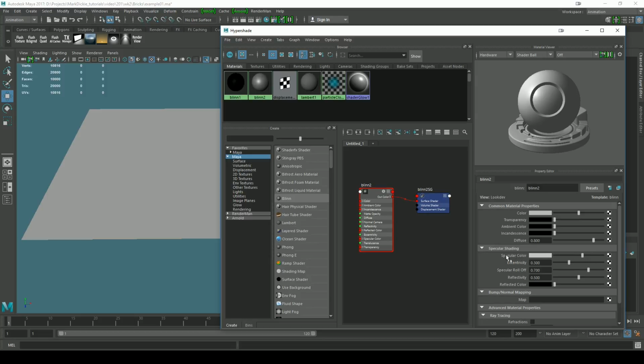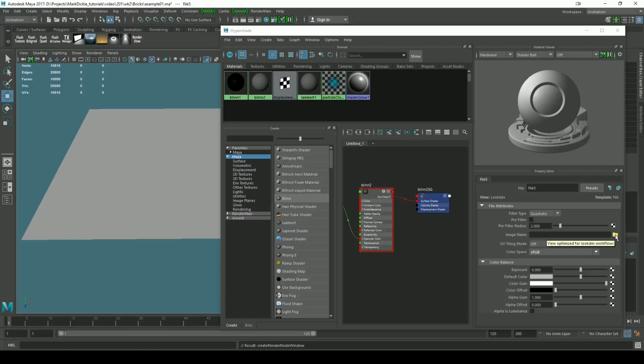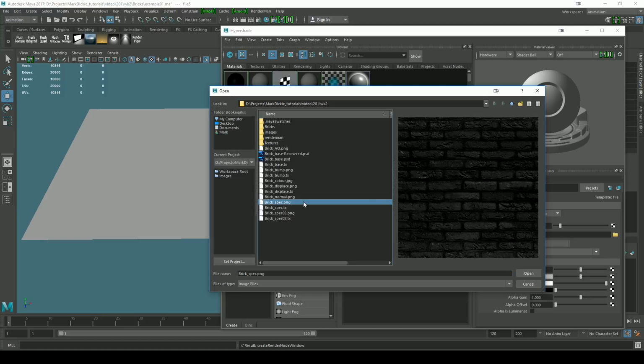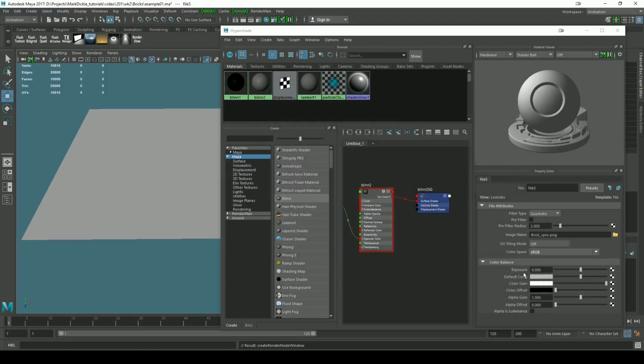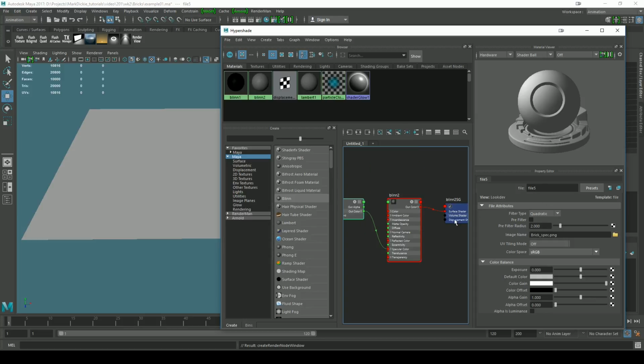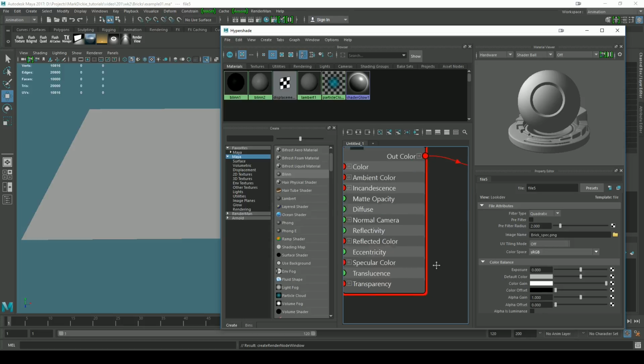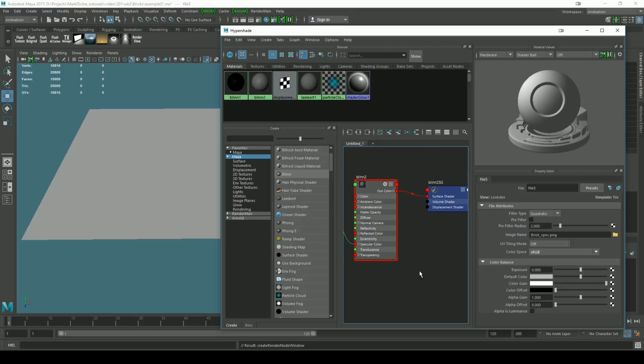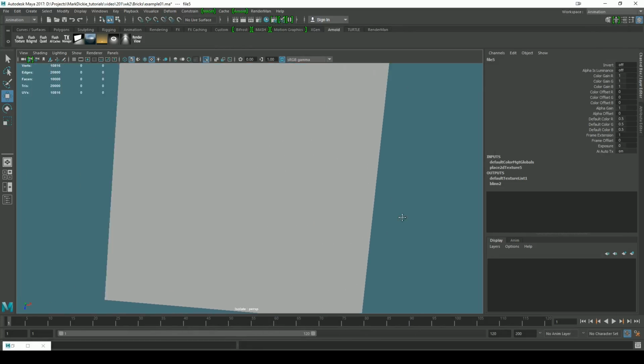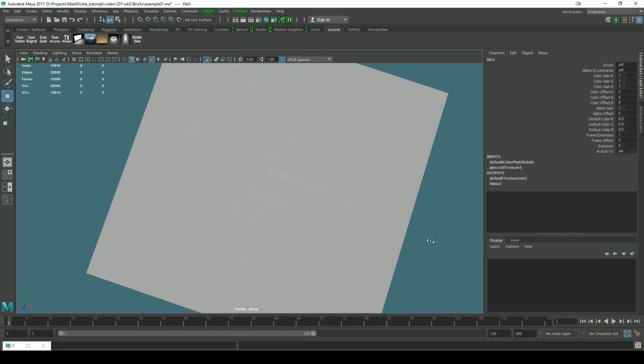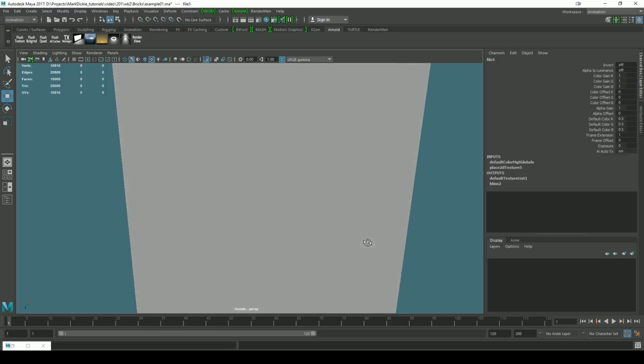Now what I want to do is plug into the specular color a file. So I'll click File. Now I can click on that folder and I can load my specular texture map. So we can see now file 5 is what I'm looking at, which is this one, file 5. And so now when I move, you can just make out some specular highlight from the bricks.